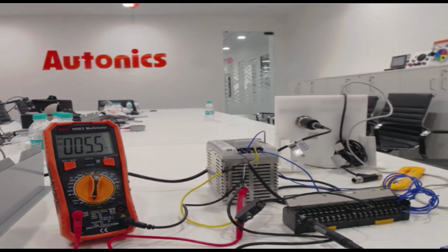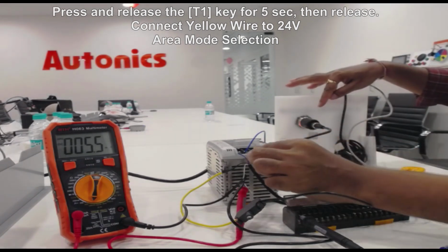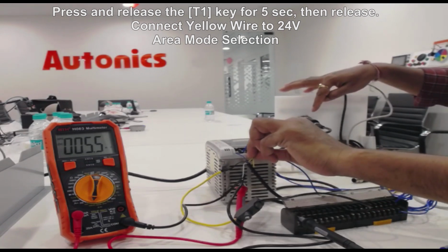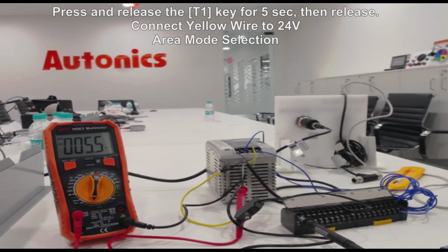So my set point 1 is done. Next, I want the area mode, for which I need to keep the yellow color wire connected to VCC for 5 seconds. So observe: 1, 2, 3, 4, 5. Okay, so now the area mode has been taught to it.